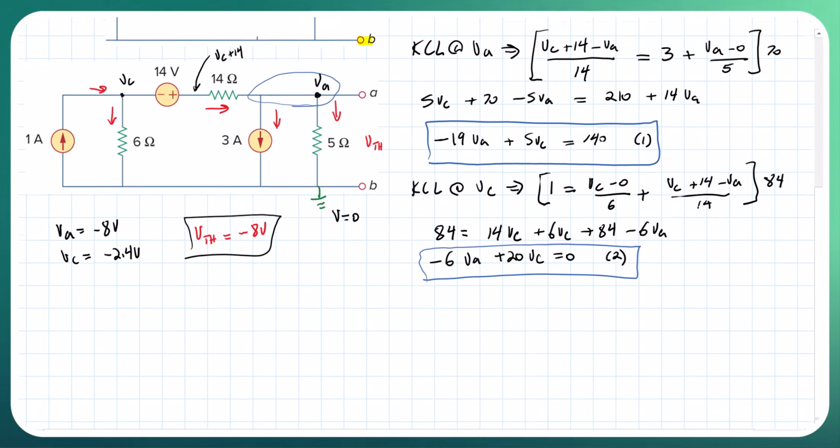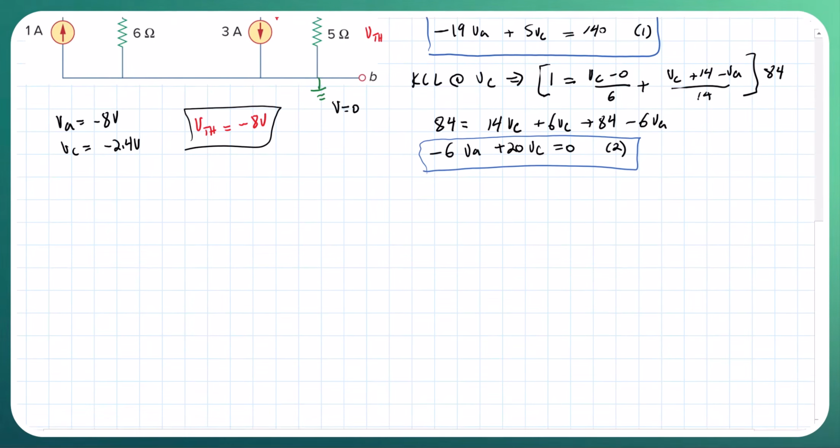Okay, so let's go ahead and draw that Thevenin equivalent circuit. There's a couple ways we can do that, but because this is minus 8 volts, I can flip the signs, minus plus, and we have a resistor there. We have our nodes A, B. Our Thevenin resistance is going to be 4 ohms, and then our Thevenin voltage is going to be 8 volts.